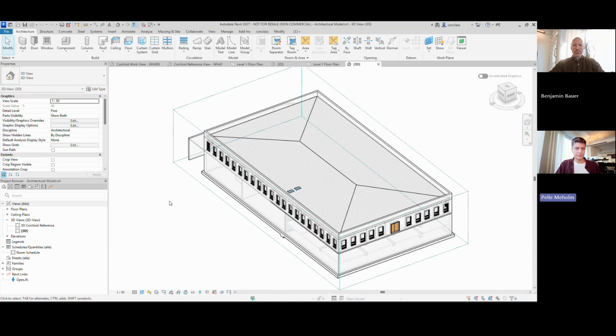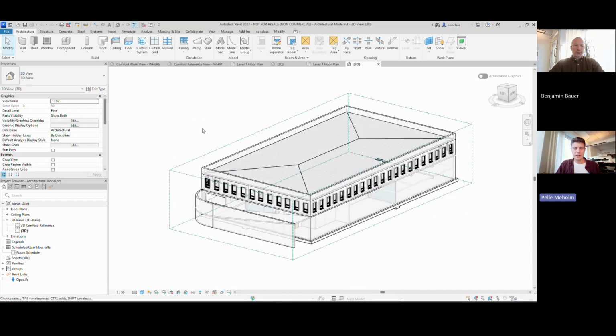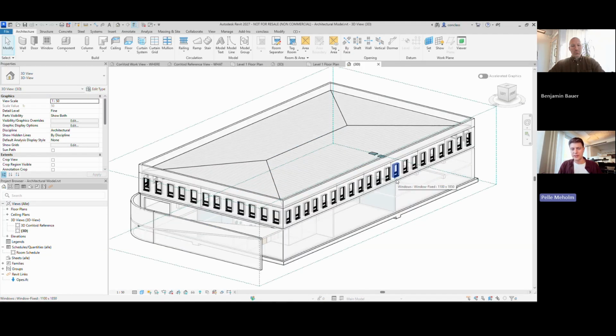Great. I'm here now in my architecture model. It could also be the structural model. And I have received an IFC file. Could also be a Revit file from an external partner. It can be a MEP engineer working in DDS-CAD, or a MEP engineer working on Revit, but without ConVoid. But now I have to adopt these openings into my architectural or structural model as well as possible.